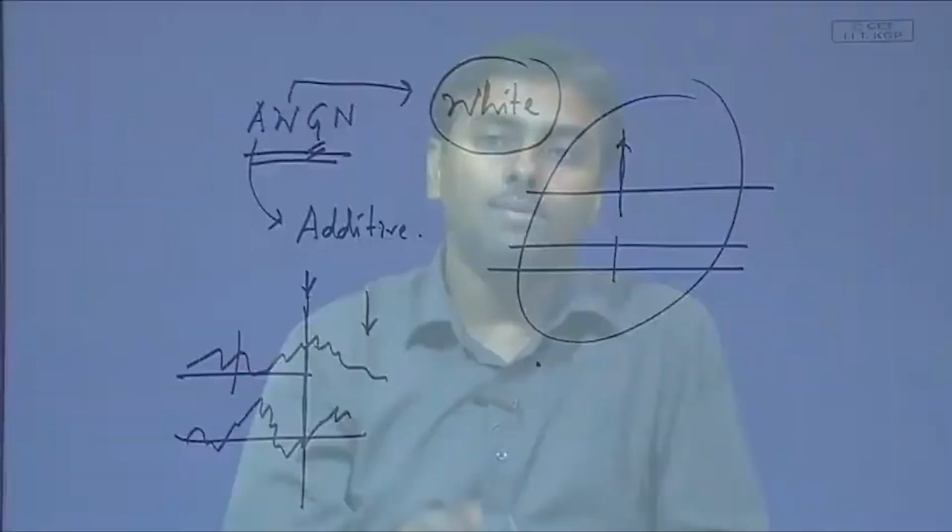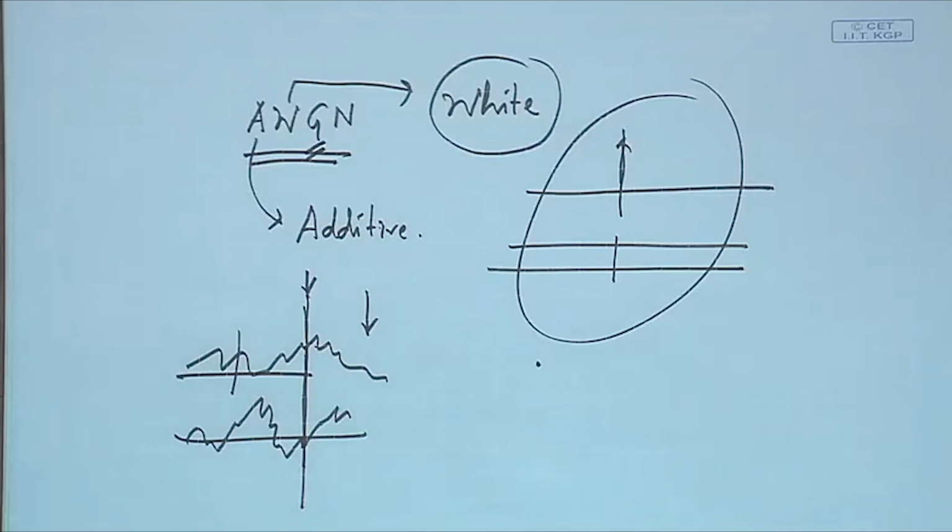The signal characterized as noise will always have 0 mean, so we can say it is characterized by a Gaussian process with 0 mean, and the sigma square is equivalent to the noise power we are thinking of. That noise power depends on the power spectral density and the band we are operating at. The way we have calculated noise power, we get that power, and the sigma square is exactly equal to it.